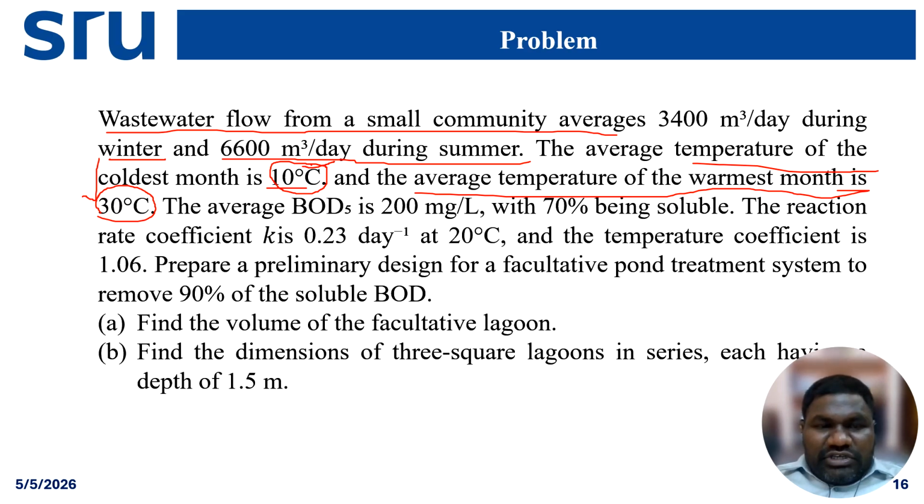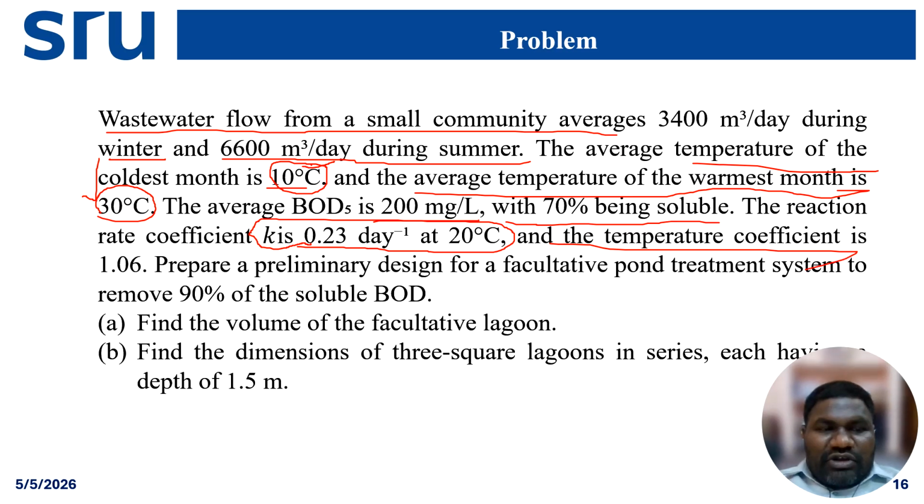The average BOD is 200 milligram per liter, with 70% being soluble. The reaction rate coefficient K equals 0.23 day inverse at 20 degrees centigrade. I mentioned the K20 value is always given in the question. The temperature coefficient is around 1.06, as we mentioned the range 1.03 to 1.12.